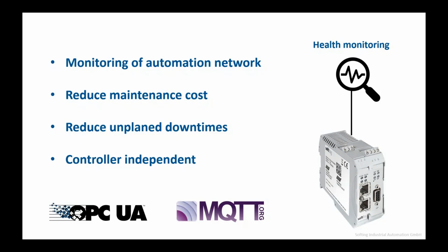A lot of protocols, especially industrial Ethernet ones, or Profinet is the best one in it, offer a lot of diagnostics data that oftentimes is not being used by the plant operators, though it could save a lot of cost that is created by unplanned downtimes. For example, you would see those coming most of the times when you are doing active health monitoring. You could reduce maintenance cost, of course, and also it's controller independent here.